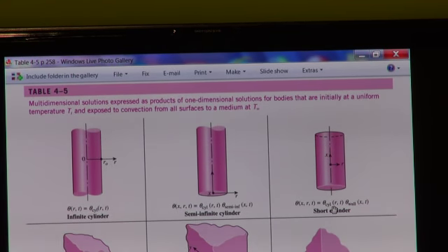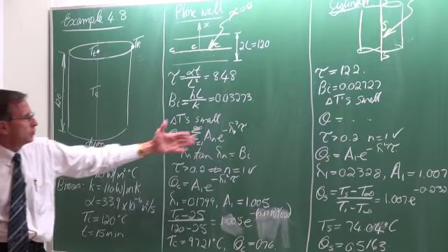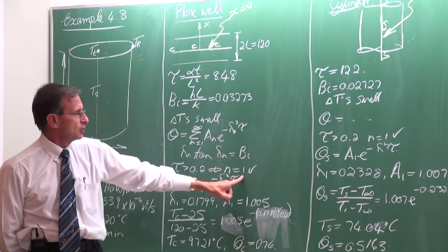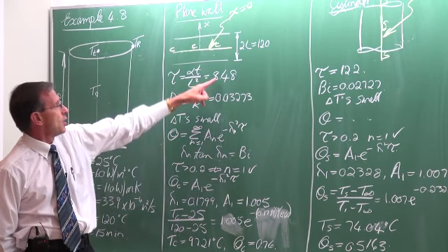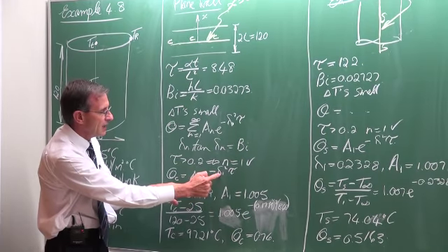Okay, so how did we do it? We calculated firstly the Fourier number, or the non-dimensionalized time, which is 8.4, and the Biot number. The Biot number tells us the delta T's are small. Okay. The Biot number, because it is small, means that the temperature difference inside the body will be small. We've looked at the equation, we've reduced it, the roots. We said we're only going to look at the first term because tau is larger than 0.2. So if we only use the first term, then the solution should be within 2%, which is good, which is fine. Okay. So in that case, we only need to use the first term, or n equal 1, so the constant 1 and lambda 1.